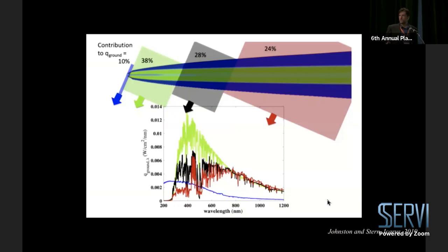You have some trade-offs going on. Near the shock, you of course have the highest temperatures in the flow, but you have a pretty small radiating volume. As you move downstream, you retain some of that high temperature and have a larger volume. And then as you go further downstream, the flow cools. So we can quantify the different radiating regions.